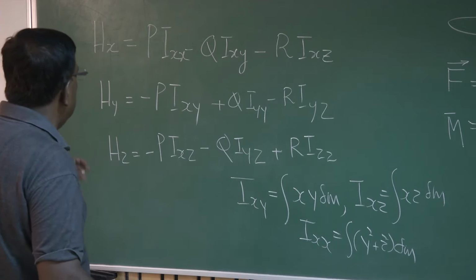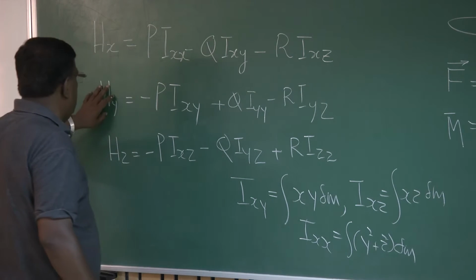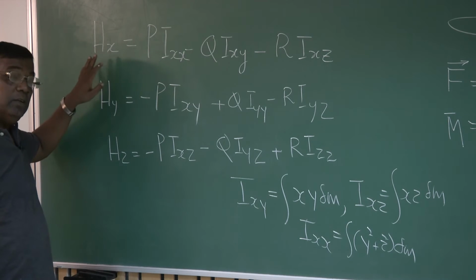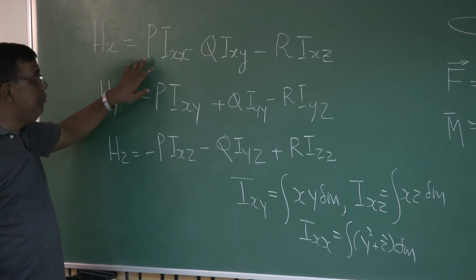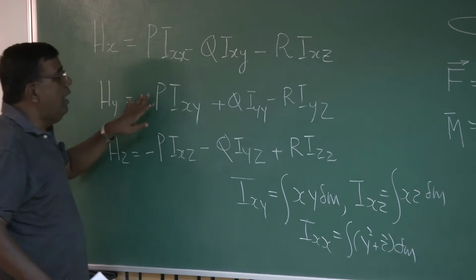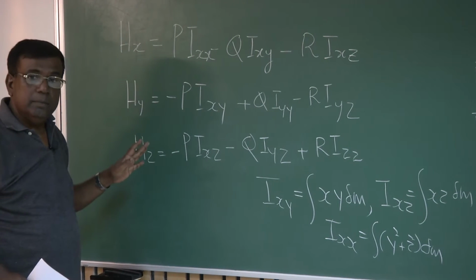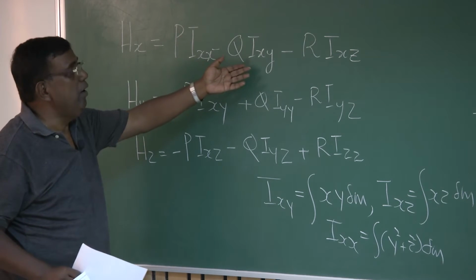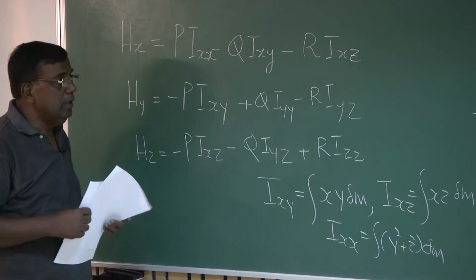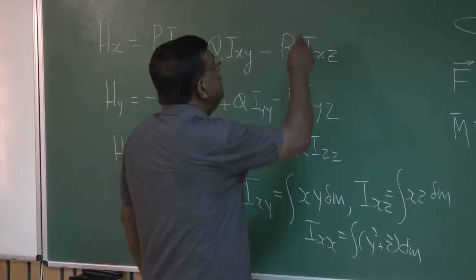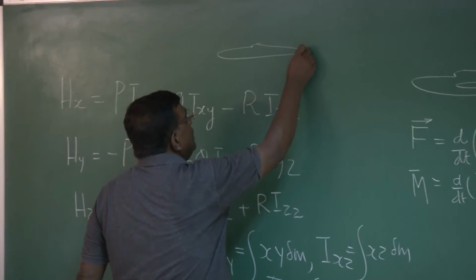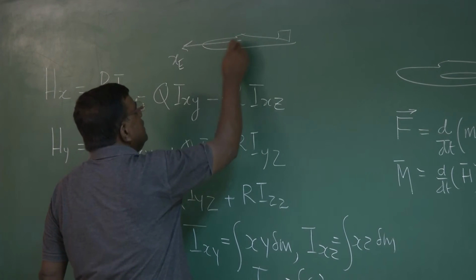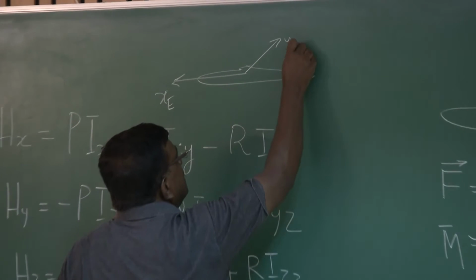are deriving all those Hx, Hy, Hz, these are with respect to the inertial frame. That means P, Q, R here are with respect to the inertial frame. Okay? Now, you imagine even this Ixx, Iyy, all are with respect to the inertial frame. Now, imagine a situation. This is the airplane. Let's say this is your inertial frame. I say Earth, X Earth, Y Earth, and Z Earth.